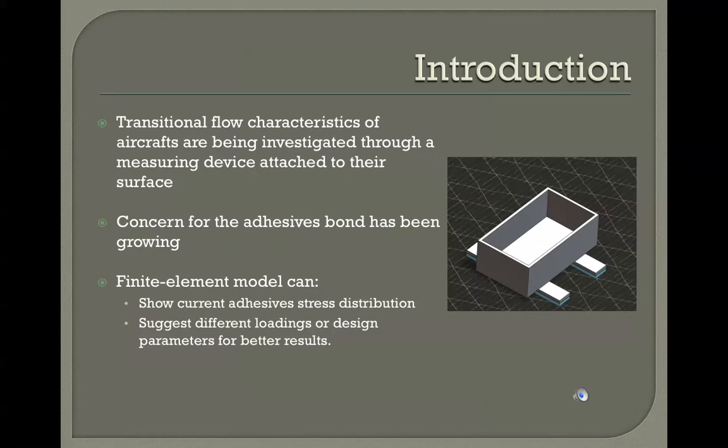In order to have a strong bond to the surface, an industrial-grade pressure-sensitive adhesive is being used. According to the adhesive manufacturer, the adhesive will fully cure when 15 psi is applied for a minimum of 20 minutes throughout the material. Concern for the adhesive's bond has been growing, and fear of its poor bond providing misleading data or yielding has become an issue.